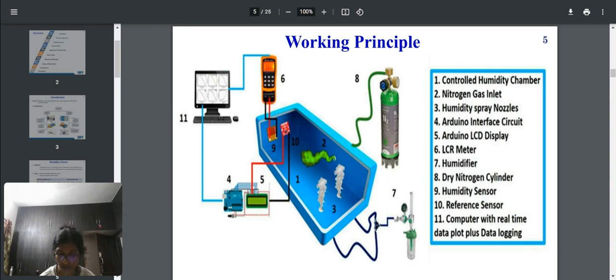They are mixed in the hydrothermal process, which increases the adsorption sites. When oxygen fills this oxygen vacancy, movement of electrons and ions takes place, which causes generation of electric current. The resistance value decreases based on this current generated. The humidity level can be measured.